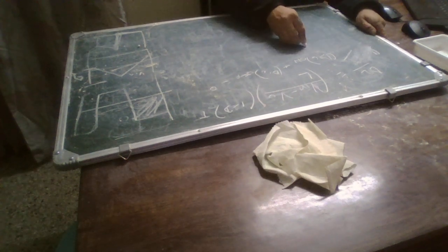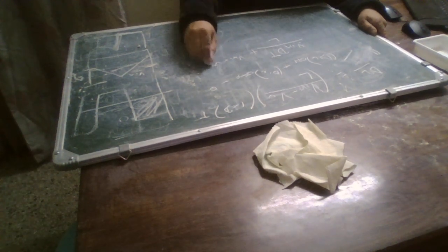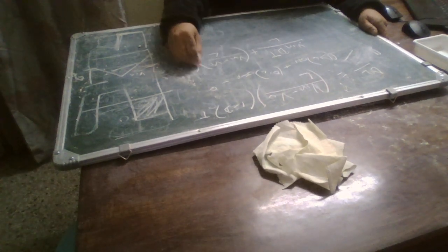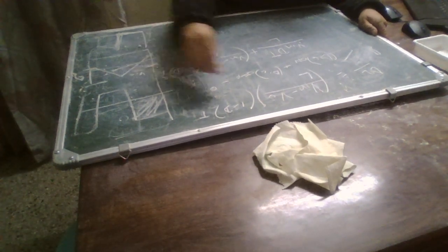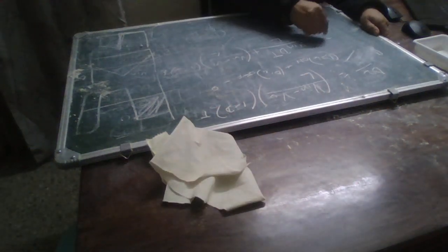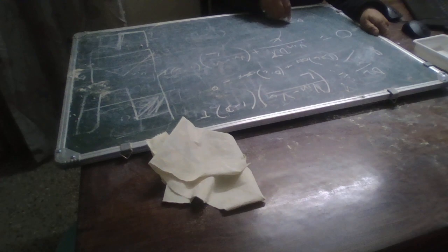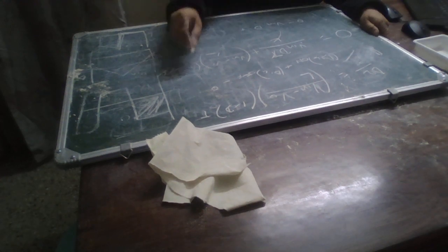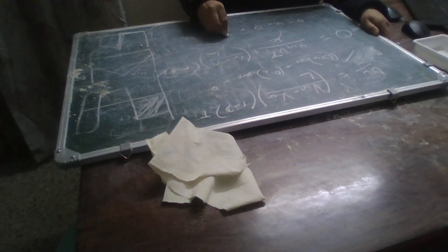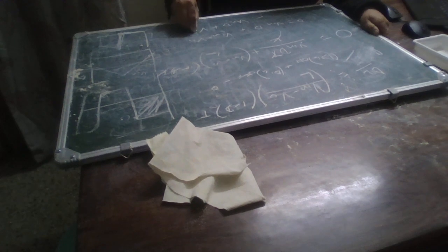So the on time, it was V input dT upon L, plus the off time, V input minus V output upon L times 1 minus d times T, and this would be equal to 0. So L will go, this T will also go. We will have 0 is equal to V input d, and I am expanding this 1 minus d here. We get V input minus V output minus V input d plus V output d. This V input d will get cancelled.